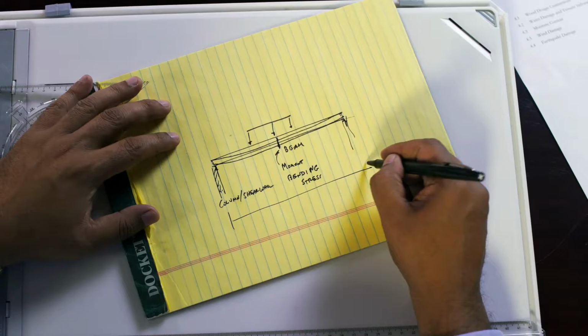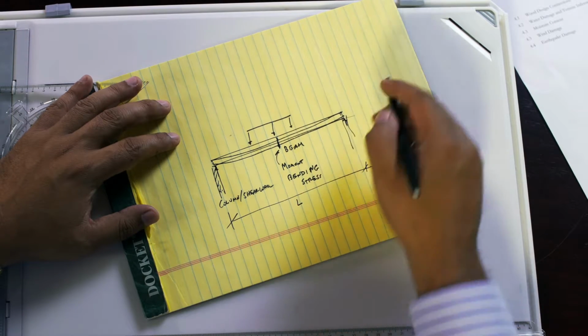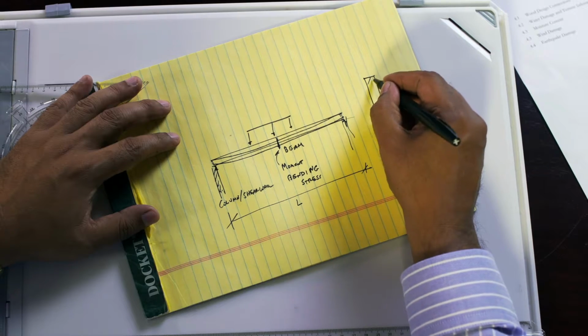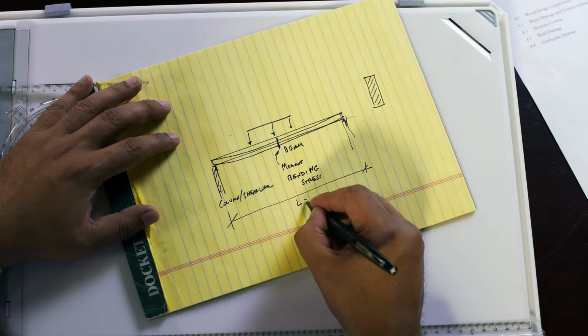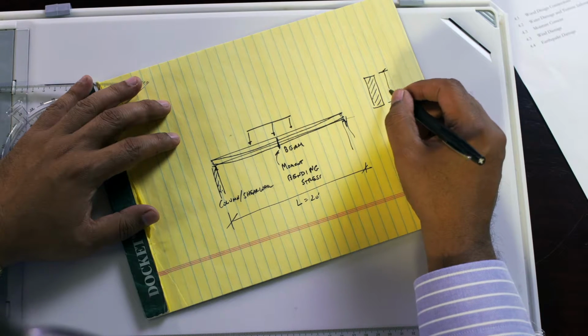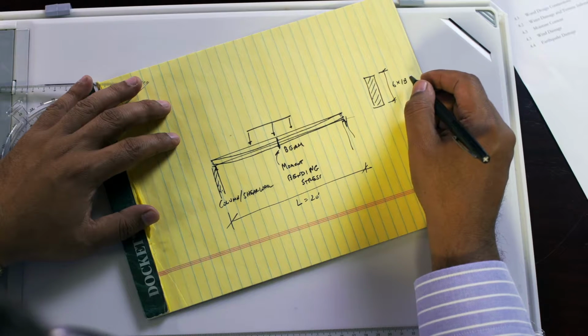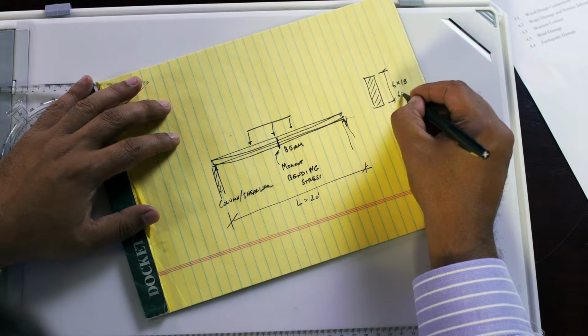So when you're designing a floor system, keep in mind that when you're designing a system of beams, the longer your span length, the bigger your beam is going to be. If I'm designing a span length of 20 feet, I'm going to be using floor joists that'll probably be on the order of 6 by 18 or 6 by 20, depending upon what the loads are, because that's a large span.